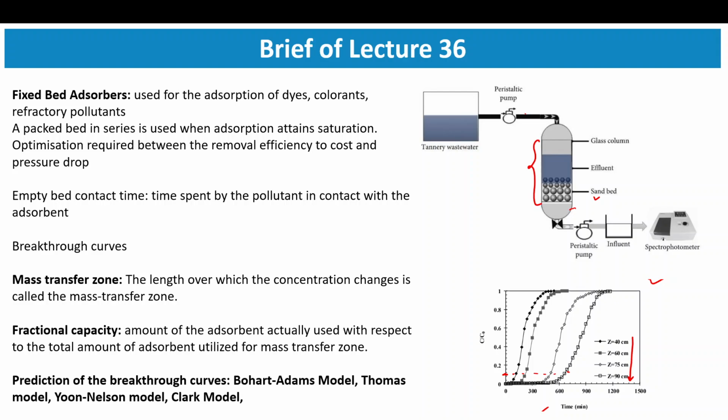By using the adsorption process, we can target some pollutants which are not removed by conventional ones like the activated sludge process. Suspended particles will be majorly removed through sedimentation, but whatever is not removed, we can try removing using adsorption.